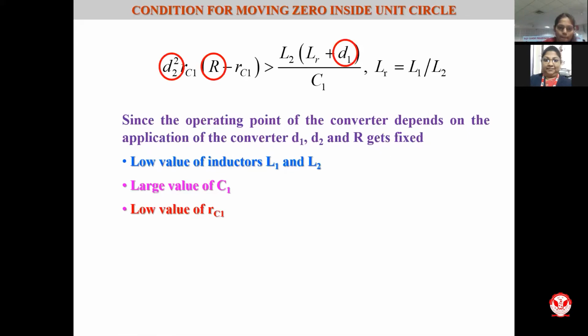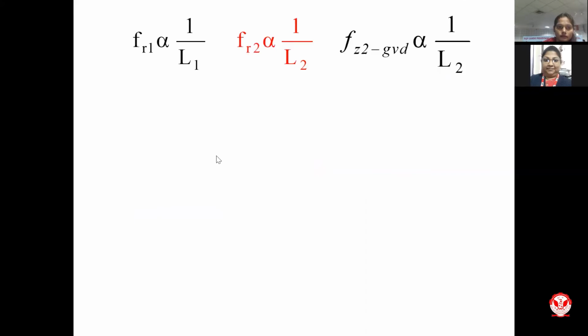So this clearly shows us, through further mathematical analysis, that the relation is quite non-linear. You cannot simply say that if I increase L, or decrease LR, or decrease C, I will be able to attain the thing. This won't work ultimately, and all these are inversely related. So it makes it quite cumbersome for manual design.